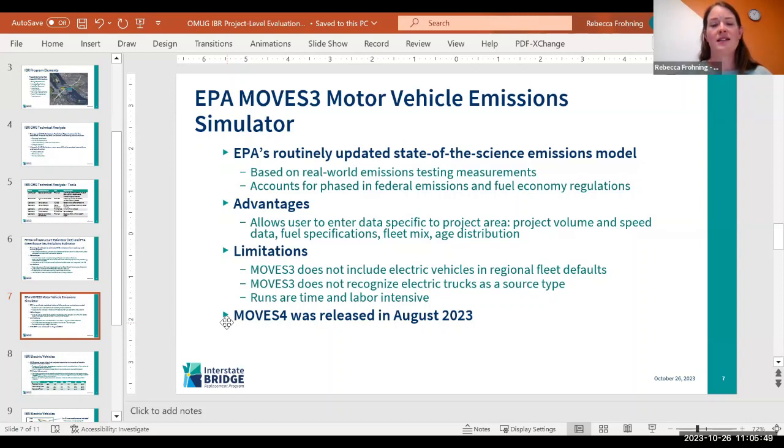It really is a model that you can either output emission rates once and then do some what if scenarios off model with those emission rates, within Excel or some other sort of programming, and that would be your best place for doing so. Just trying to figure out how to make MOVES run for your electric vehicle situation within the model would be very time intensive.